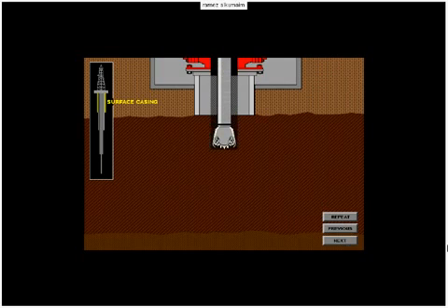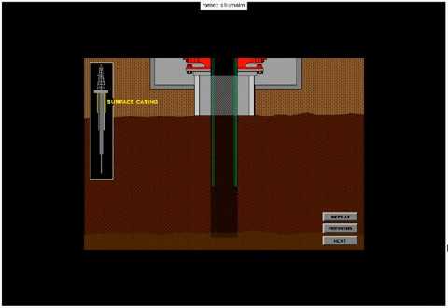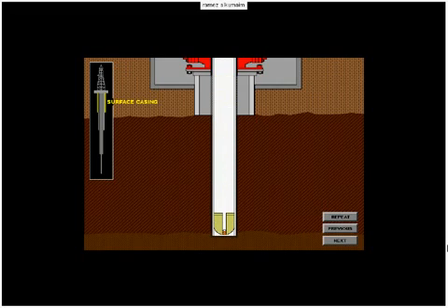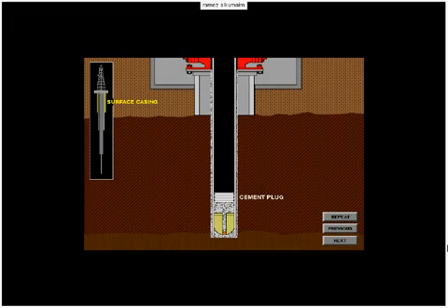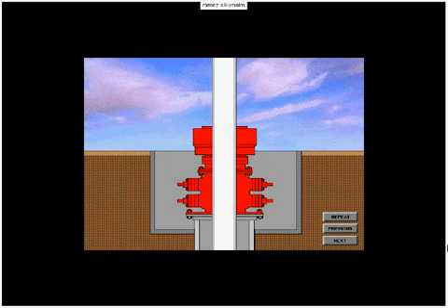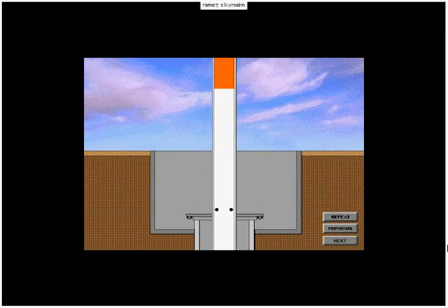Upon completion of the surface hole, the surface pipe is run to a specified depth to isolate any freshwater, saltwater, oil, or gas zones within that depth range. The surface pipe is run and cemented in place back to the surface. A cement plug is left in the surface pipe so that the diverter system, or BOP system, may be disconnected or nippled down safely. After the diverter, or BOP system, has been nippled down, the surface pipe is drained. Then the adapter flange, or drilling flange, is cut off.